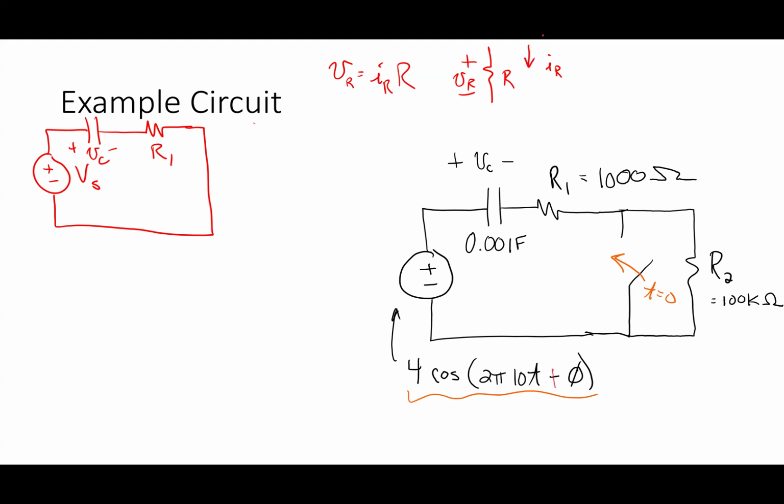So if I have a capacitor, it's a similar thing. There's an Ohm's law for it. Here's V sub C. Here's I sub C. And I know that I sub C is equal to C times the derivative of V sub C. That's the Ohm's law, basically, of a capacitor. All you got to do to approach this problem is I need to know that fact. Once I know that fact, it's basically just using KVL to deal with it. So I'm going to do KVL. To get the differential equation, what rule do I use here? KVL or KCL?